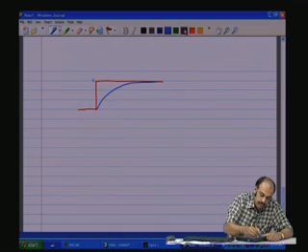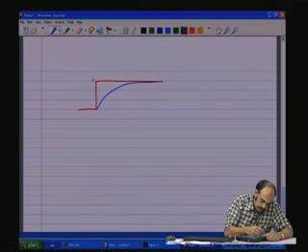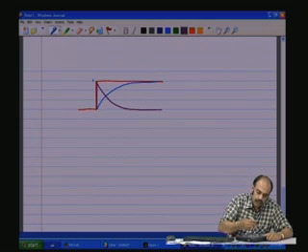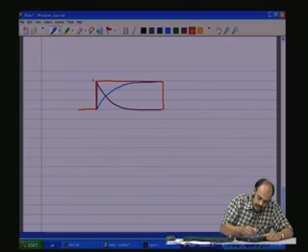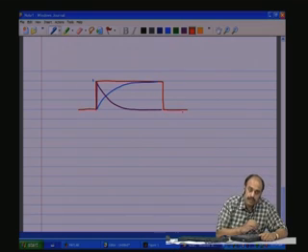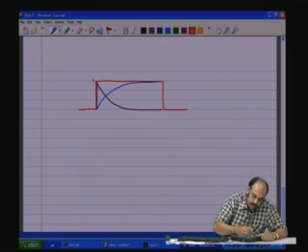What happened to the voltage across VR? It was a value which started from here and then starts going gradually down to 0. Now, let us say we close the step, that is, we bring the step back and then make it 0. So, Vi becomes 0. So, what happens to the voltage across the capacitance? So, it starts decaying like that gradually to 0.